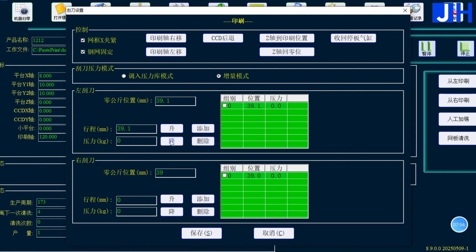Should the machine malfunction and the stencil squeegee fail to apply the solder cleanly, we should first investigate other potential causes. If necessary, adjust the downward movement depth of the template scraper. The default value is 39.1. Should this prove insufficient, the drop distance may be incrementally reduced by a small amount, such as 0.5 mm. This has been lowered by 0.4 mm.